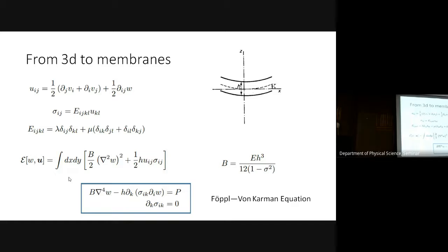This nonlinearity is coming because something like this, you see, can have a very large deformation globally, whereas the deformation is very small locally. So a small dimensional object embedded in larger dimension gives you geometric nonlinearity. The material itself is not elastically nonlinear. It's the geometry that makes the problem nonlinear.